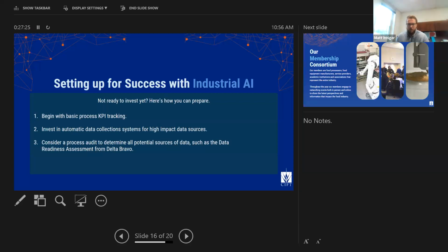And this ties us back to our initial webinar in this series, right? Design a process that is generating good data and build a culture of collecting it and using it. The number one way you can do this is begin with really basic process KPI tracking, and that can be manual. That can be, twice a month you run out to your packaging line and count the number of packages that are coming off a minute, right? Really basic, but important to have some idea of what sort of data your process is generating and know where you might want to look for inputs to such an algorithm in the future.